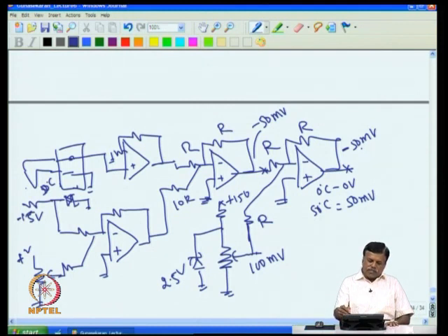If the heater is on, assume that heat is on, then if this temperature goes up, then this minus also will go up. Then as more and more minus comes, this will also come down. When the temperature becomes 100 here, this will become minus 100, and this is plus 100, then this again will become 0. So what we have done is we have generated error voltage.